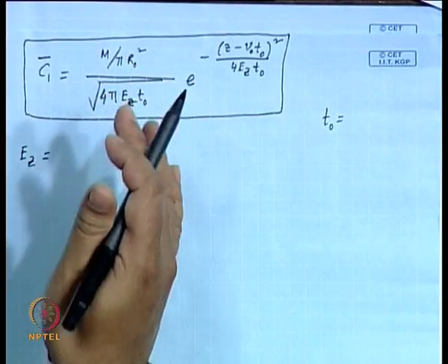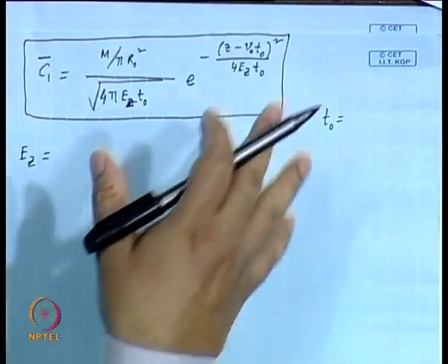When we talked about the diffusion of a small spot of tracer in an infinite medium, we started with this expression, but instead of Ez we had D, the diffusion coefficient, which is something we know, a bulk property. Then we said, if we go to Taylor dispersion, we continue with the same form, but instead of D we have a dispersion coefficient Ez, and the expression for Ez you already know, V naught R naught square by 48 d. Now, what researchers are saying is that we continue with the same compact functional form. However, we work out how this Ez would be affected because of these complications.